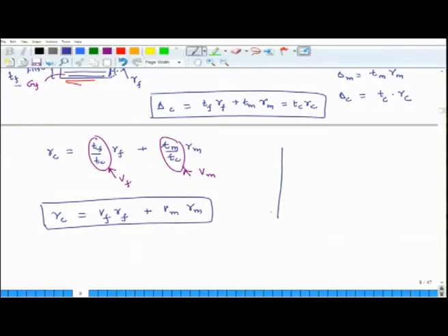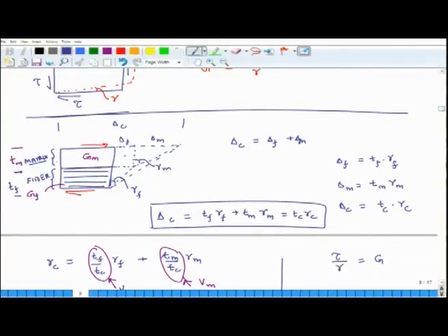But gammas are changes in angles, and their values are very small. The fiber by itself is isotropic, the matrix by itself is isotropic, and for isotropic materials we had said that tau over gamma is G. Now, what is the shear stress in the matrix? It is tau.